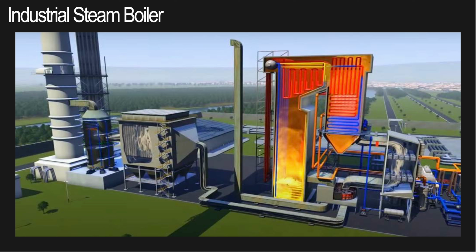It's going to go preheated. It's going to go to saturation. And from saturation, it goes to the steam drum. That's where the transformation of liquid water into steam happens. What will happen is water will go down in something called downcomers. And because of the heat, it will basically vaporize and it will go up into something called risers.